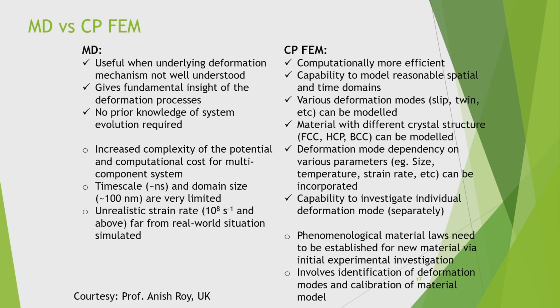Till now, molecular dynamic simulation is not being done on very practical problems, and CP-FEM is computationally more efficient. It has the capability to model reasonable spatial and time domains. Various deformation modes can be modeled, like slip, twinning etc. Materials with different crystal structures can be modeled. Then deformation mode dependency on various parameters can be incorporated. The capability to investigate an individual deformation mode is also there. These are the advantages. Compared to molecular dynamic simulation, it will take much less time, but the disadvantage is that phenomenological